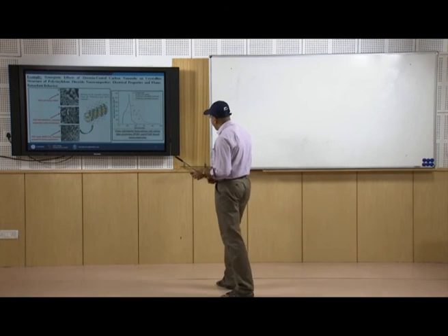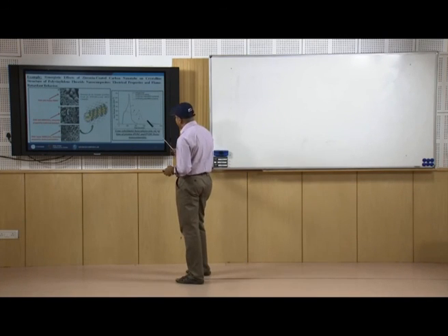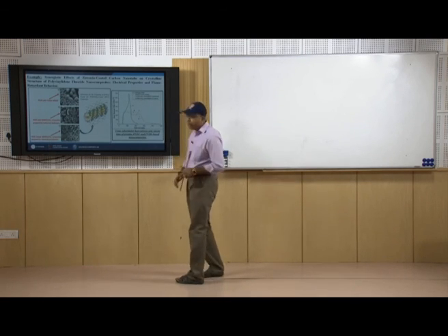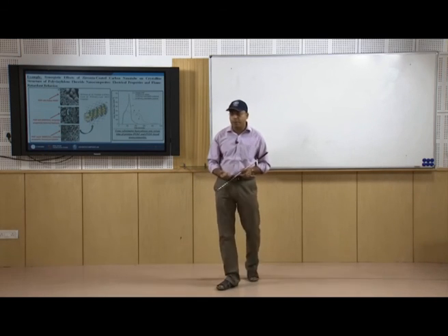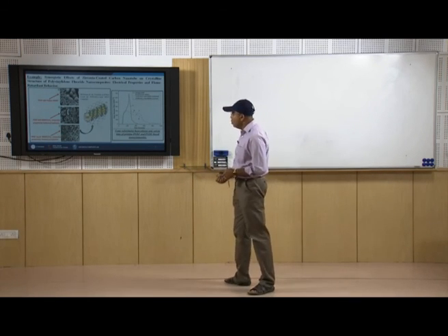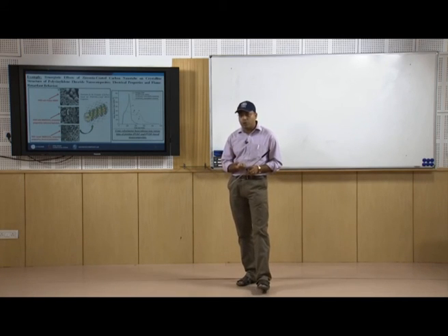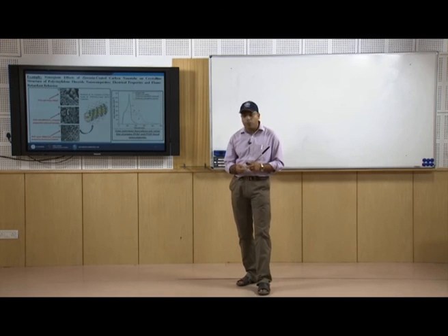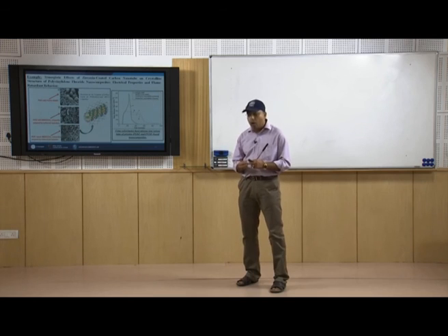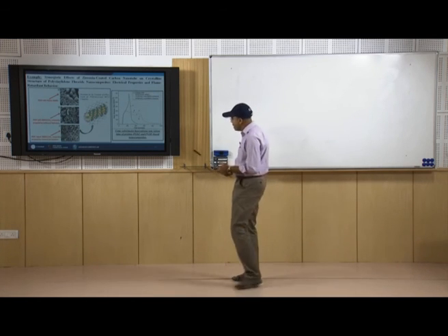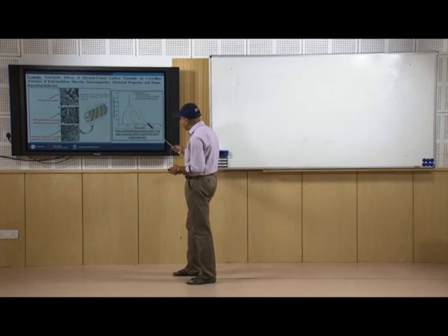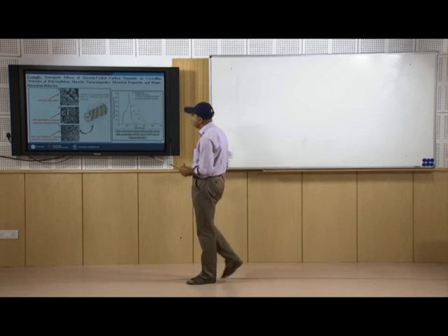But when we apply this kind of coating materials inside the matrix, we have seen that almost for the D samples, and then when we go to the C samples, it gives the maximum time that the material can sustain, and also the heat release rate for this particular material is very low. So, the important point we are showing here is that when we use some kind of nano coating on the CNT, automatically the material's heat release rate decreases, and not only that, the sustained temperature of that particular material increases.